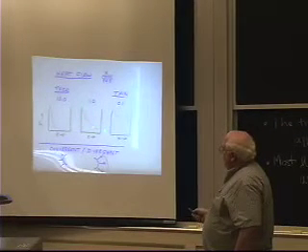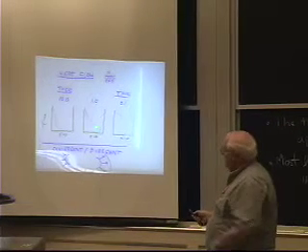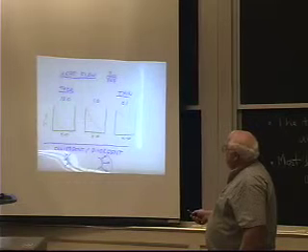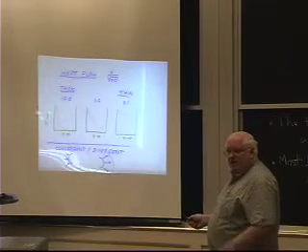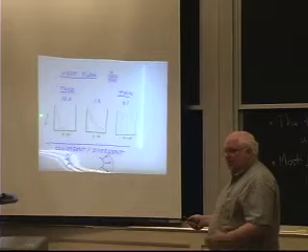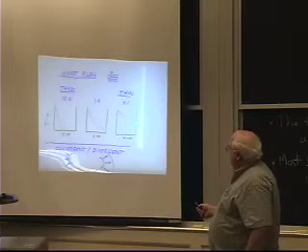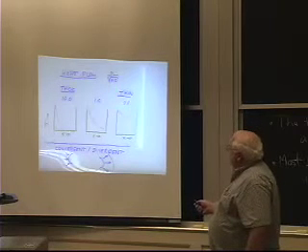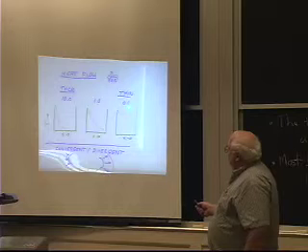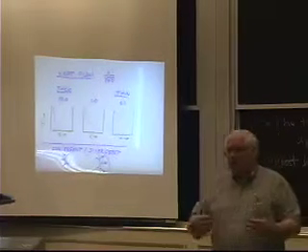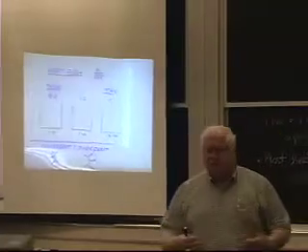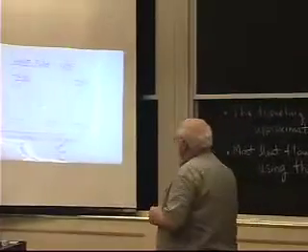Now that's a complex system and you probably need to go to a fancy model. But when you have a thick solution, if the Fourier number is 10, the heat doesn't penetrate all the way through. It's not saturated with heat. If I have a thin sheet, in the same amount of time the Fourier number will be small, and essentially the part gets saturated with heat and has a relatively uniform internal temperature. And most of the time, that's all you really need to know.